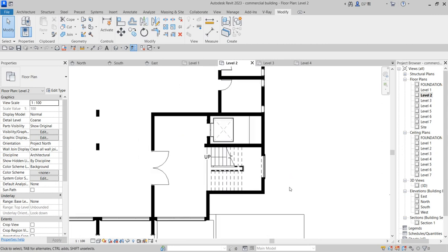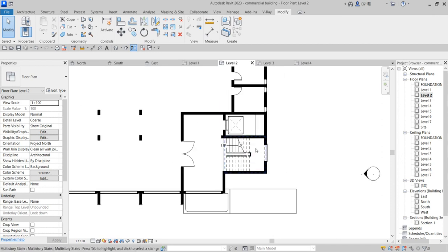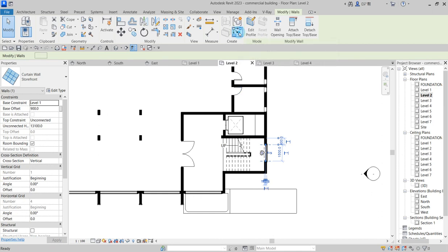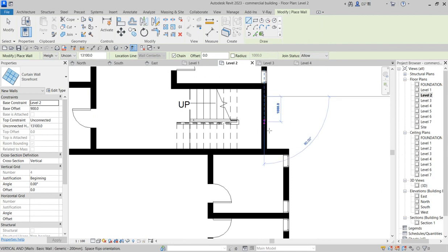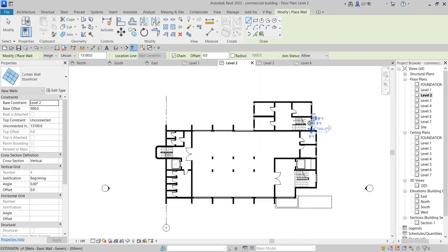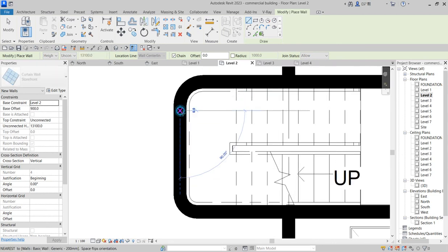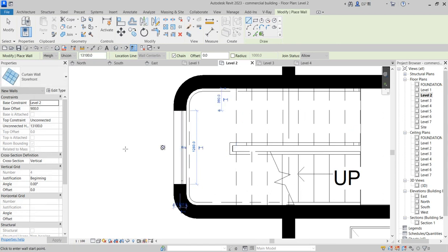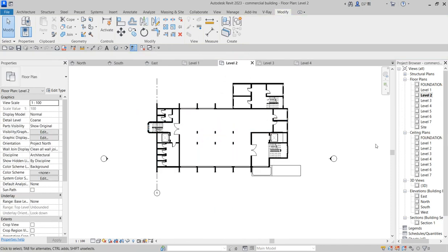So now what we want to do now is to put windows, the stair openings to where it's supposed to be. So I'll start from here, say create similar. So at this point I'm putting so that this stair will receive its own opening. The same thing will happen to this space as well, so that it will receive its own opening as well. So I will go to elevation to check them through and work them out.